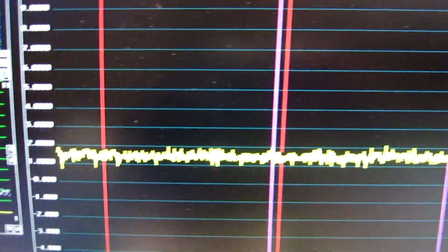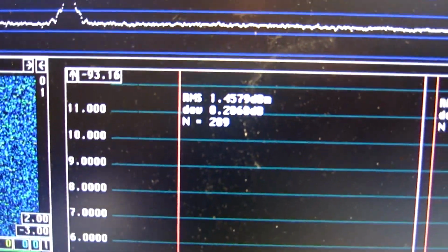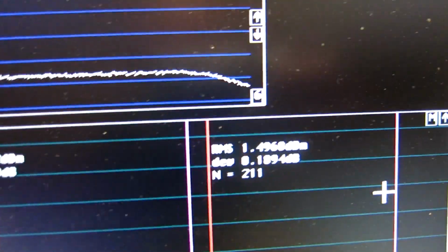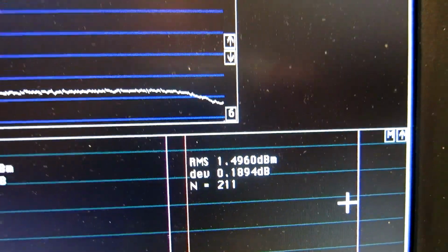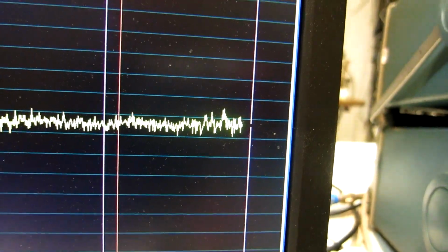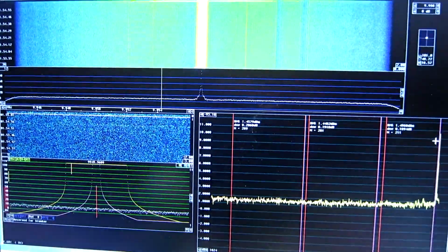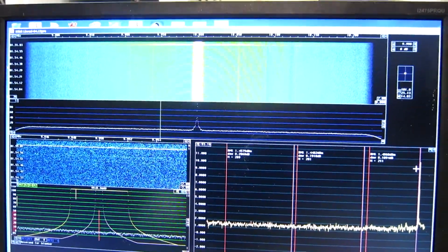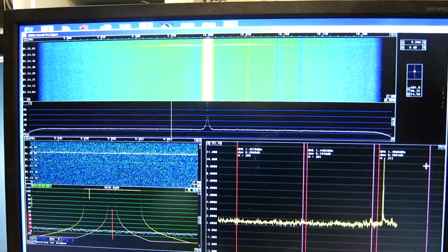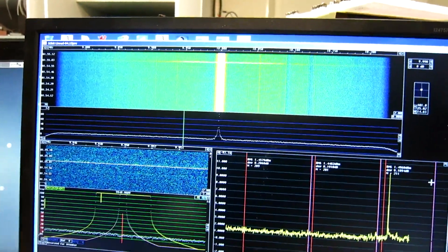The noise floor also looks more stable, and if I measure it on different parts or in time, I see very similar values. Well, here's some instability. Of course, instabilities can occur in resistors, that means attenuators, connectors, and of course also in the oscillator and mainly the tube sockets.